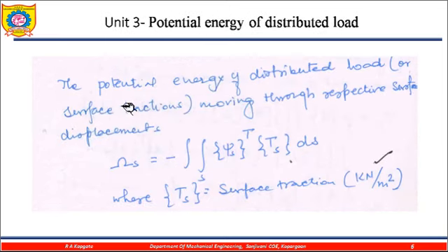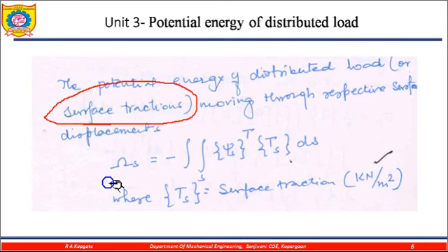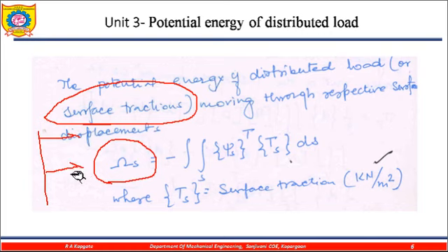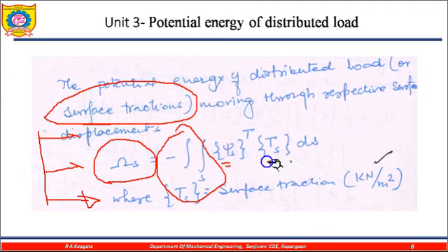Then the traction load, the surface traction loads. Whatever traction forces we are applying, the term is equal to minus the double integration, because the traction force is applied on surfaces. Since it is applied on surfaces, this is not the integration over a volume but the integration over a surface. So it is the integration over S of ψ, my displacement function, multiplied by the traction force at ds.